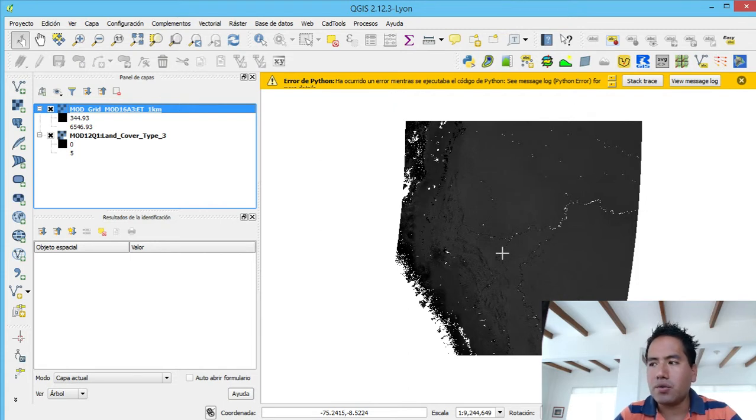What you are seeing here is just a representation of the raster, but it is in a spatial reference system with coordinates that are not very compatible for spatial analysis. So one of the first things you have to do is convert it to WGS84 in a GeoTIFF or GRD format.